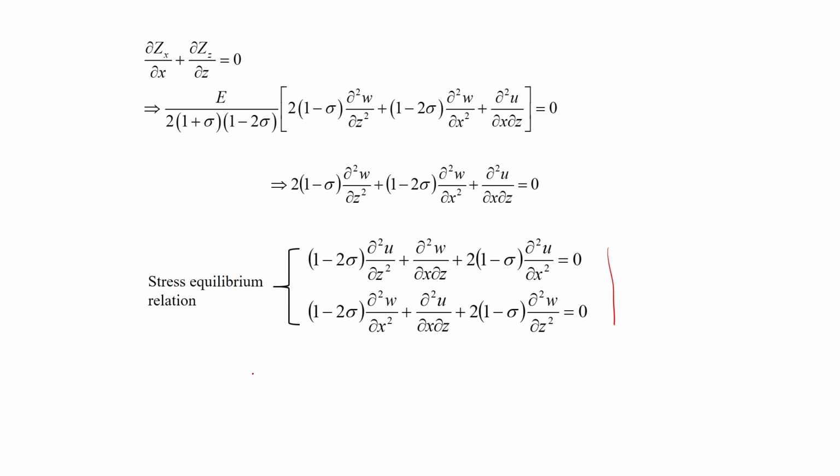So, that is actually del u by del z plus del w by del x, that is equal to minus P, the hydrostatic pressure, divided by K, where K is the bulk modulus here. Okay. So, do not confuse this K with the K that I derived in the earlier lecture, 4 E star by 3.